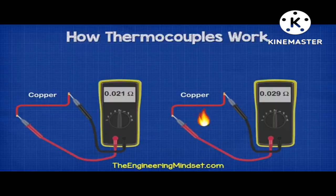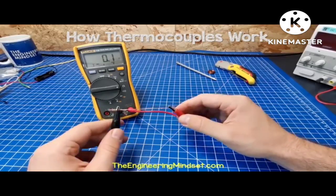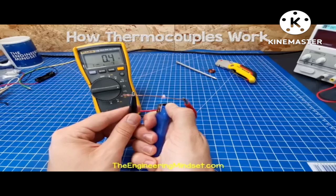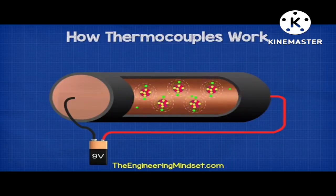The temperature of the material will change the resistance of the material. Most conductors will increase in resistance the hotter they get. That's typical of metals. For example, this copper wire shows a resistance of 0.1 ohms at ambient temperature. But when heated with a flame, it increases up to 0.9 ohms. This occurs because as the atoms and the molecules become excited, they're going to move around a lot. So this makes it harder for the free electrons to get through without a collision.